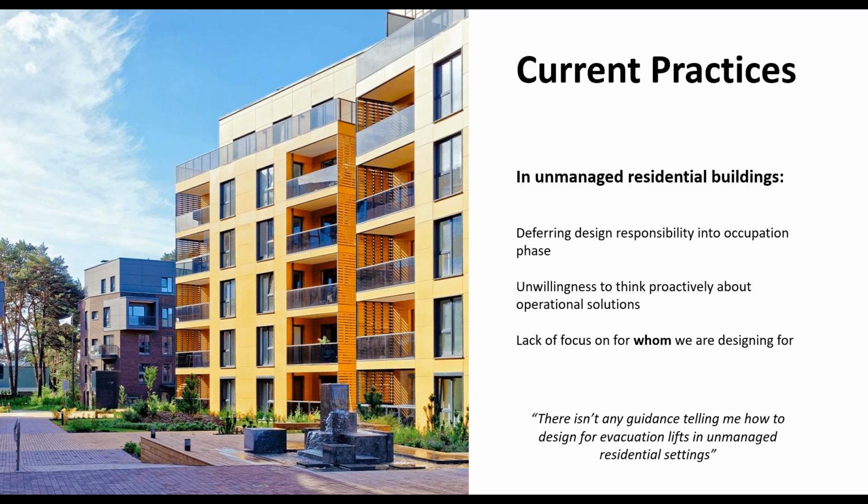We have seen a deference of that design responsibility being kicked into the occupation phase. What I mean by that specifically is that we have seen a number of fire strategies presented where the challenge of delivering an evacuation strategy that incorporates the use of an evacuation lift, where there is no on-site competent person to manage that evacuation, as per the guidance in 9991 and 9999, is kicked into the long grass with de facto lines such as "a suitable evacuation strategy should be developed once the building is occupied."